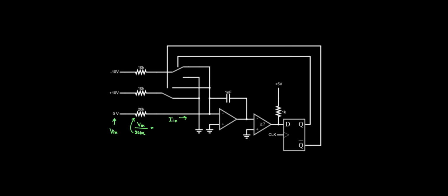Input voltage is converted to a current, which is then integrated by a capacitor, with the process being controlled and idealized by an op-amp. Infinite integration is unfortunately not possible in the real world, so the feedback loop constructed around the integrator periodically injects controlled amounts of charge into it to keep it from saturating to either rail, by simply measuring if the integrator level is above or below 0, and injecting charge pulses of the opposite polarity.